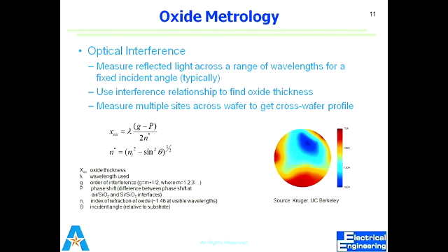Okay, so that was all about the oxidation systems. We talked about horizontal and vertical furnaces, and we talked about RTP, that is rapid thermal processing. And now we will talk about how to measure the thickness of oxide. The measurement of the thickness of oxide is very important, because if I want to etch or pattern the silicon dioxide, I should know about the etch rate and the thickness of the oxide. Exactly what is the thickness of the oxide until I reach an etch stop, and exactly what is the etch rate of that